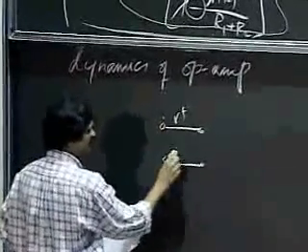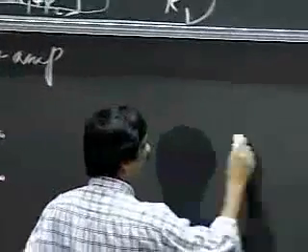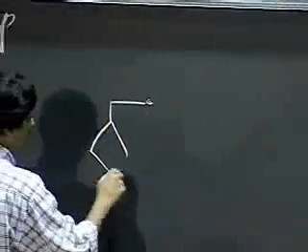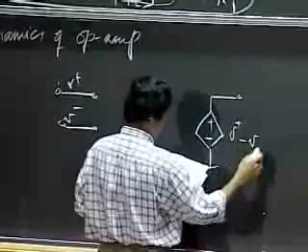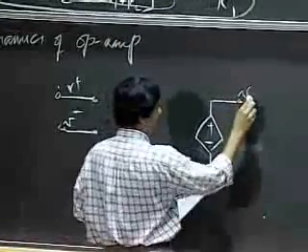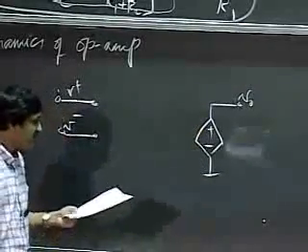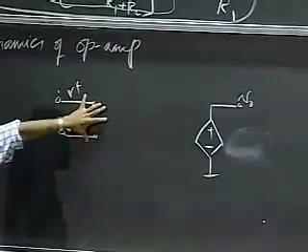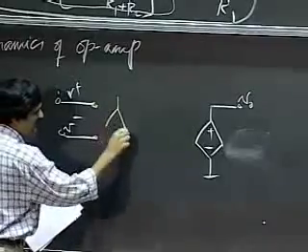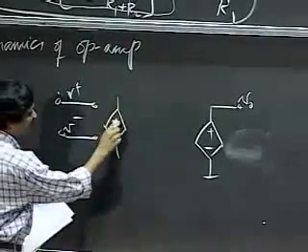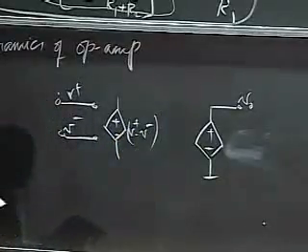So V plus and V minus. Okay, so this is what we've seen before, two terminals and a dependent source that amplifies the difference input here by a large amount. Instead what we're going to do here is something slightly different and interpose the following circuit in the middle here. So this is a model to model the dynamics of an op-amp.